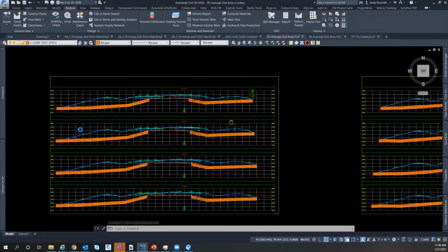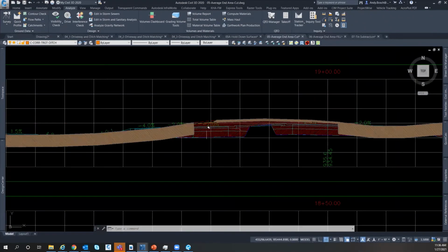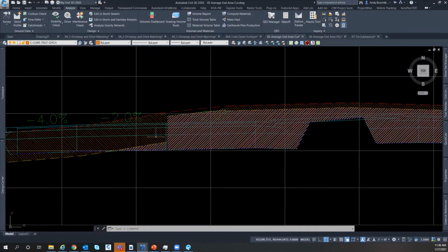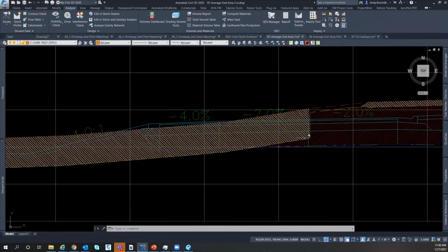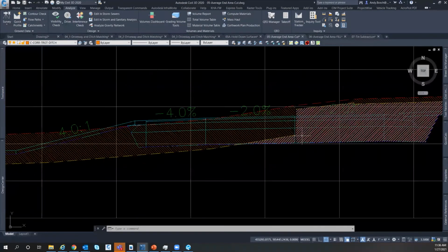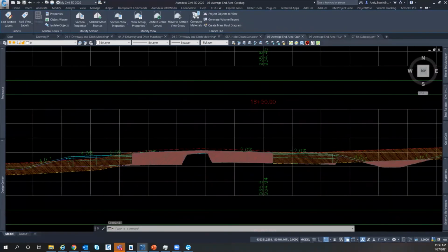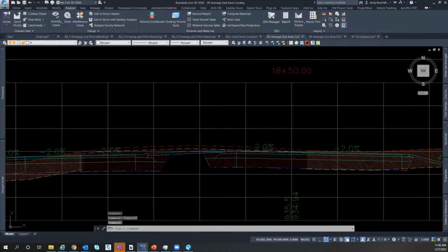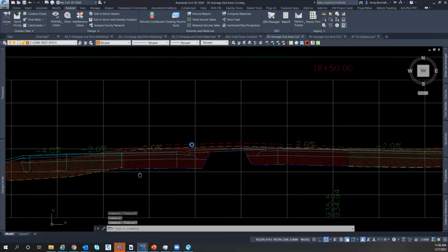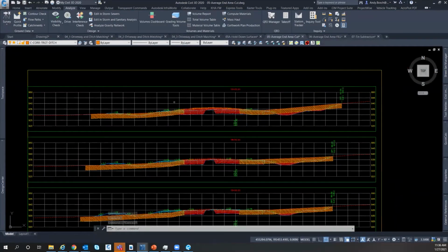So now you can see that as I go through here, I'm getting my earthwork analysis to happen. It's using my hold down surfaces. It's figuring out my topsoil stripping areas here. I had a lot of topsoil removal on here. And then I'm getting into my actual earthwork numbers on some of these here. This is like good material that I can still use on the project. So we've got all this hatching happening. This is good. I can print this out. This is showing in color.